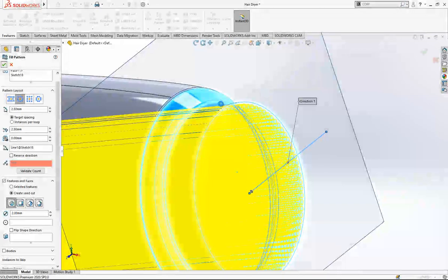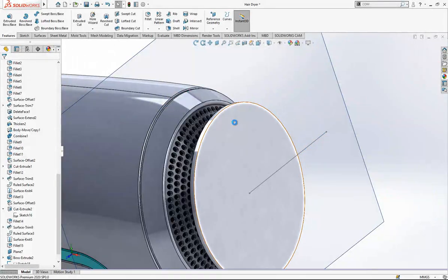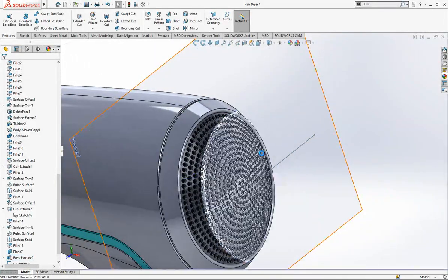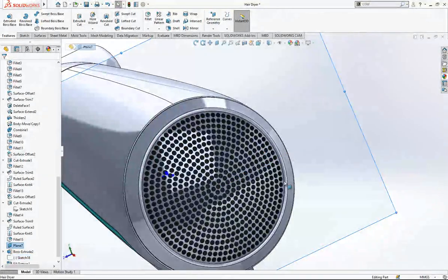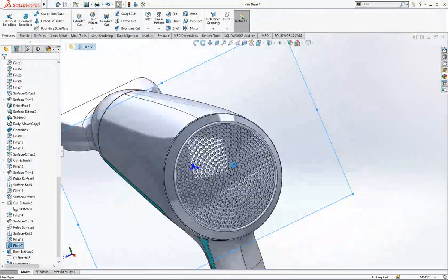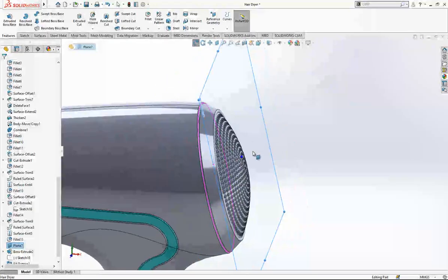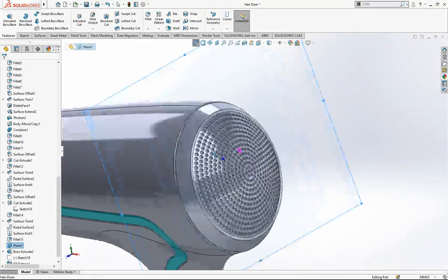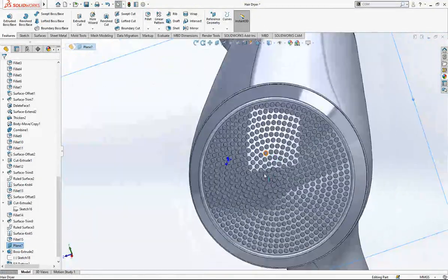It has nothing to do with the rest of the model. Otherwise, I will spend in this area a lot of time for creating this pattern with SOLIDWORKS. It is really terrible. But with this way, it is quite nice. Also, our surface shape is not that much curvy. It works because in the projection, distance is a little bit changing, but it is here compensatable.